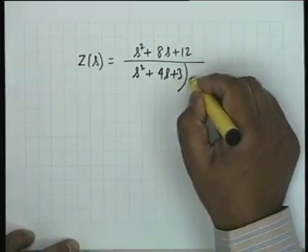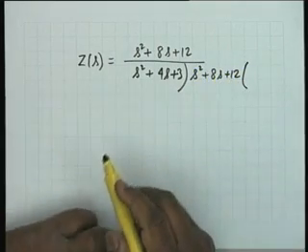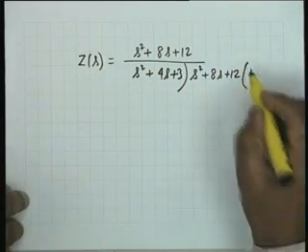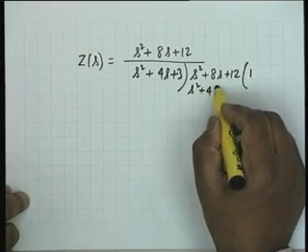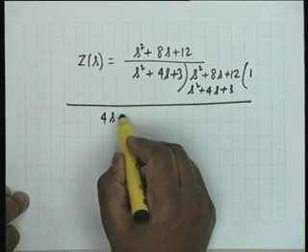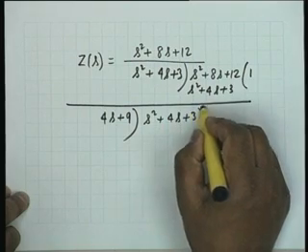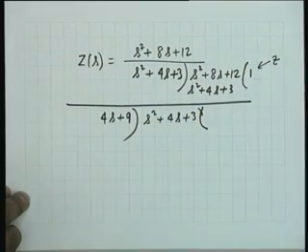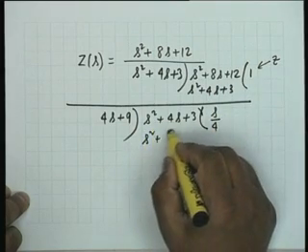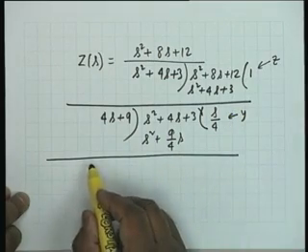All right. Now I start continued fraction expansion. S squared plus 8S plus 12. The logic is that we are removing the infinite frequency constant value from Z of S. So I get 1, S squared plus 4S plus 3. Let me bring the remainder here: 4S plus 9, that divides S squared plus 4S plus 3. Do not forget to indicate the dimensions. This is a Z. Then I get S by 4, S squared plus 9 by 4S, and this is a Y. So I bring the remainder here.